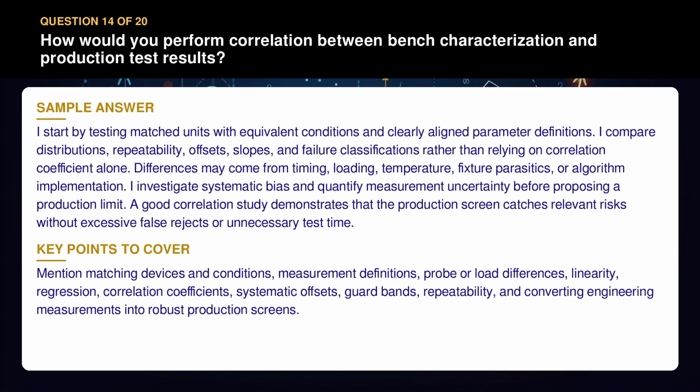Mention matching devices and conditions, measurement definitions, probe or load differences, linearity, regression, correlation coefficients, systematic offsets, guardbands, repeatability, and converting engineering measurements into robust production screens.